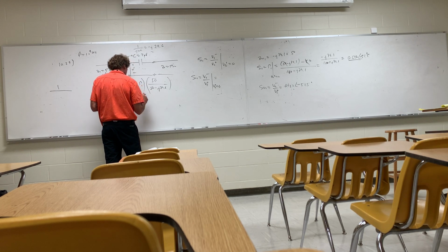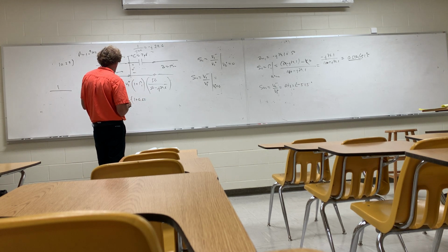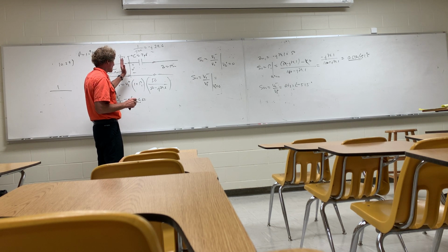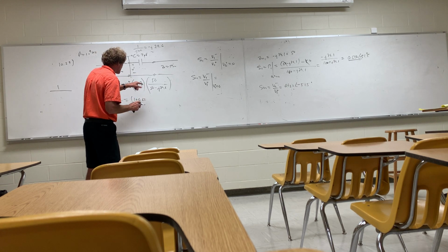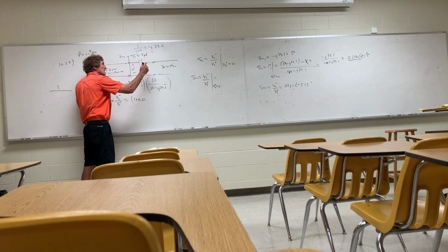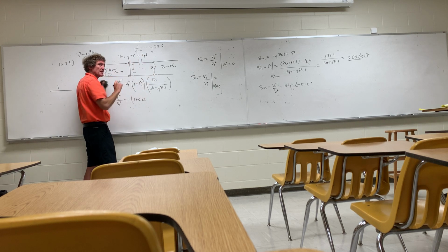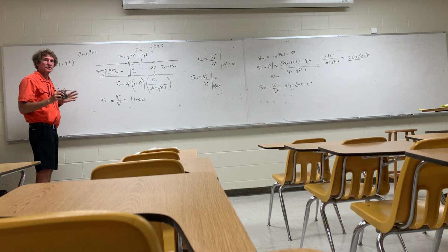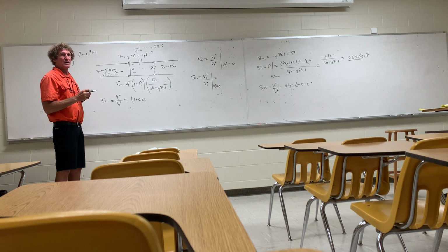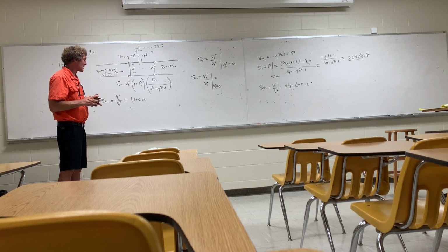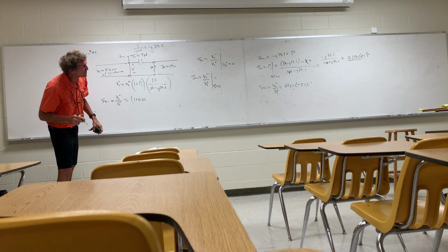Is it not 100 minus j79.6? Pardon me? What did you say? Right there at the bottom, it's 50 over 50 minus j79.6. Shouldn't it be 100 minus j79.6? Well, what we're looking at here is voltage division, right? Once we have this, this equivalent resistance is 50 ohms. So what I want to do is find the amount of voltage developed there. That would be 50 over 50 plus this, times that. Sorry, I wrote the capacitor down as 50 plus that, that's why. Don't ever trust me when it comes to this. Always look suspiciously at me. It's the best way. And that's 51, minus 51.5, right?